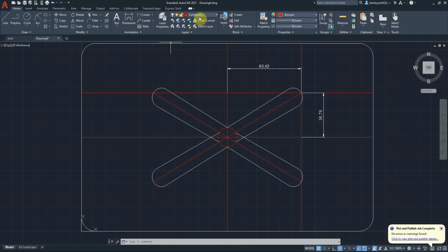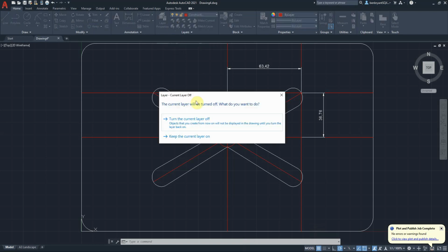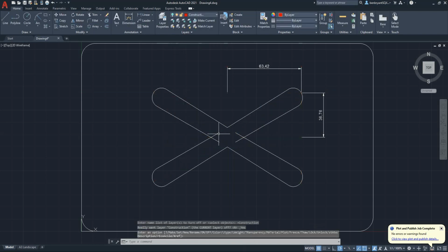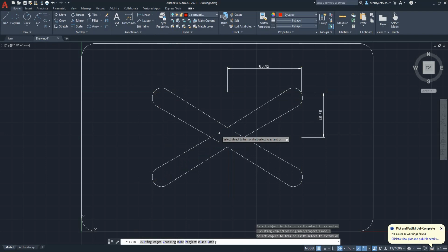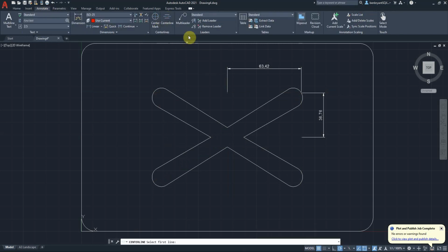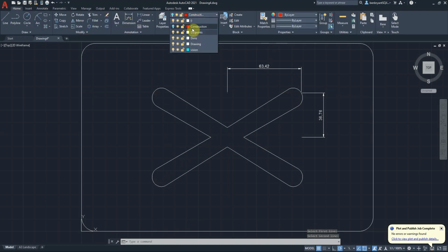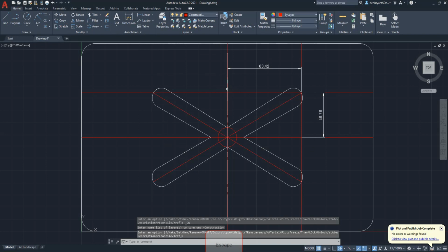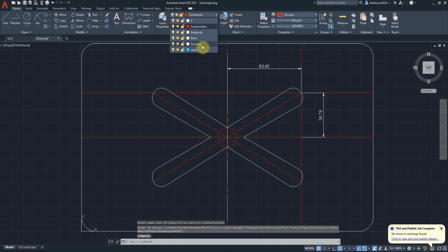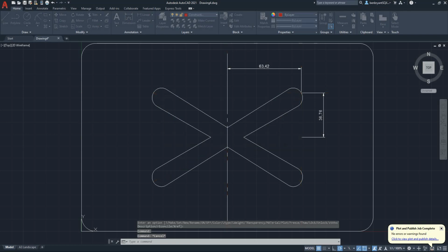Okay, lastly then, I'm going to remove my construction lines, to turn them off. Okay, now I'm just doing a bit of trimming up on my edges like so. Okay, now I need to put my center points in, so I'm just going to go into annotate center line, so this one and this one. Make sure I'm in the right layer, so I'm obviously in the wrong layer then.